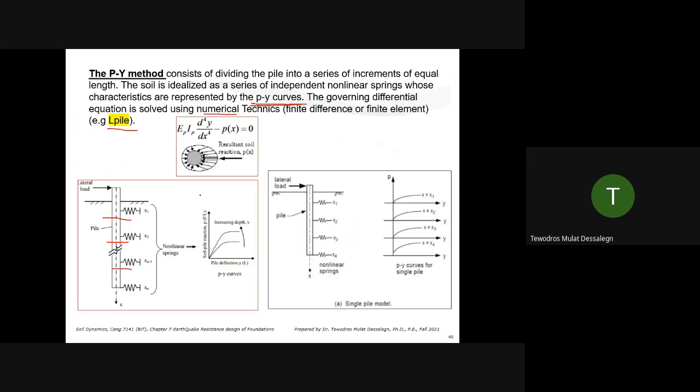Researchers developed these curves. The governing differential equation is solved using numerical techniques such as finite difference or finite element methods. And using this, if you have a pile to be designed for a lateral load, you can use software like LPile. It's a well-known geotechnical software. Because if it is vertical load and moment, you can do it even manually. But if it is a lateral load, now it gets complicated.